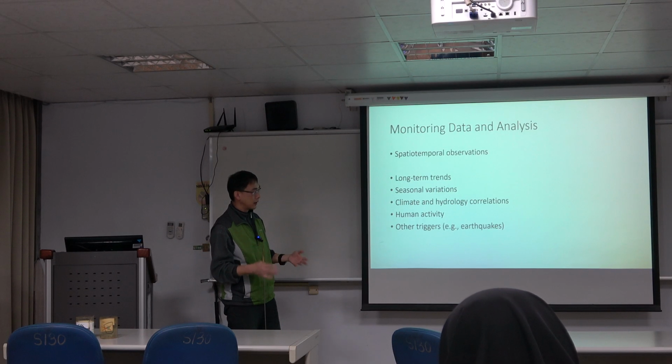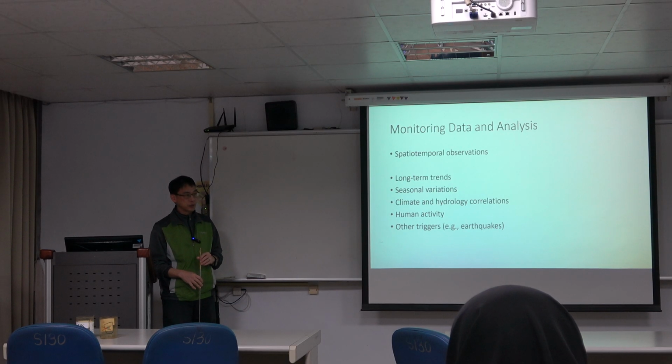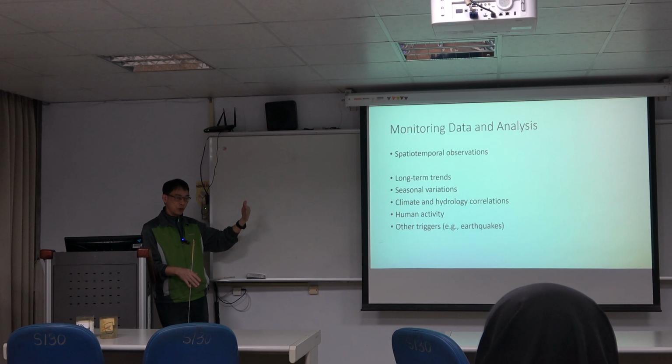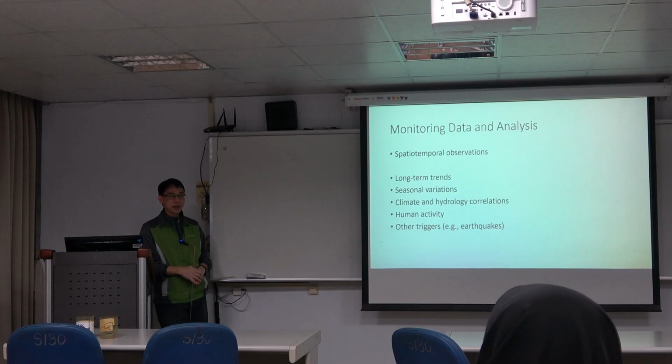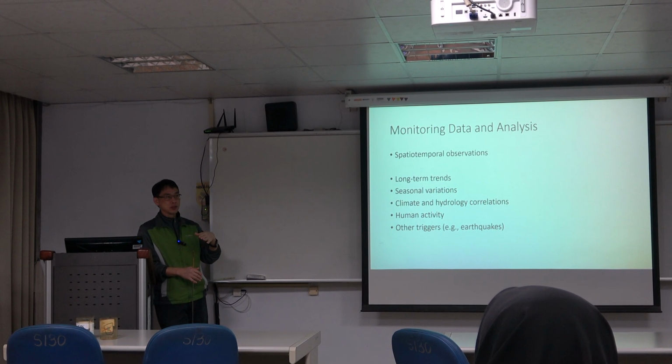Maybe in later lectures, I can try to show some of the observations we made, where Yuhao did the assessment. We see a lot of level decline or uplift, and the decline could be more than 10 meters. It depends on the hydrogeological conditions. Like in eastern Taiwan, the hydrogeology is mainly gravels, very coarse materials. And another factor is that they are tablelands, so the elevation is relatively higher than the mean sea level. So after earthquake shaking, it is easy to have damage to your sediment system.